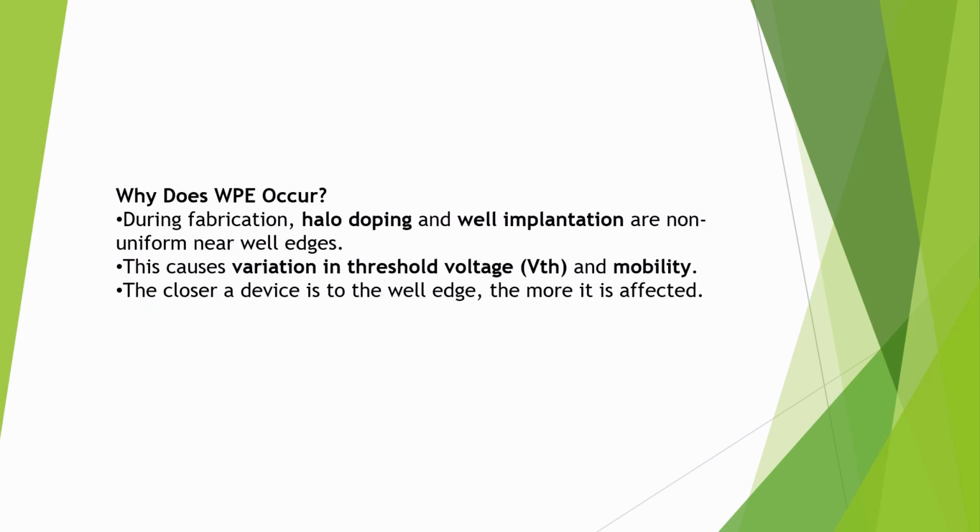Why does WPE occur? Mainly during fabrication, halo doping and implantation are non-uniform near the well edge. This causes variation in threshold voltage and mobility. The closer a device is to the well edge, the greater the effect.